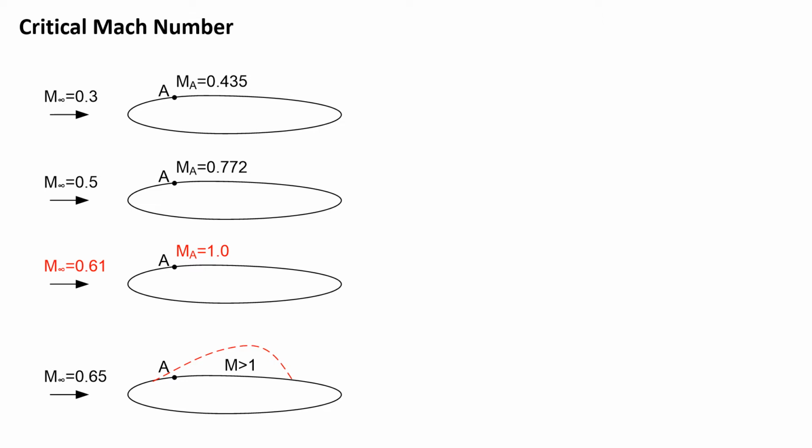Okay, and also through the discussion for the airfoil across the transonic Mach number regime, we know how to determine the critical Mach number. We just look into the detailed flow field over the airfoil surface and find out if there is only one single point, or a very small region, with sonic Mach number.